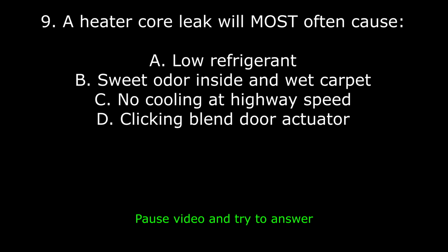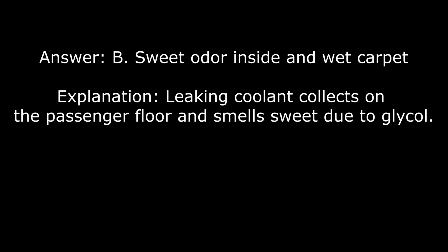9. A heater core leak will most often cause A. Low refrigerant, B. Sweet odor inside and wet carpet, C. No cooling at highway speed, or D. Clicking blend door actuator. Answer: B. Sweet odor inside and wet carpet. Explanation: leaking coolant collects on the passenger floor and smells sweet due to glycol.